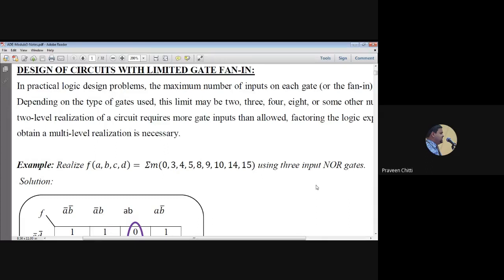Because directly you will not get F. When you use the SOP K-map, clubbing with zeros, you are going to get F bar only. That's what I was telling. First tell me the answer for F bar. Then we'll see how to get F again. I'll tell you a simple technique. In fact, you need not write all the steps of De Morgan's theorem. Directly, in a single step, you can write F from F bar. That's a method I'm going to explain now.